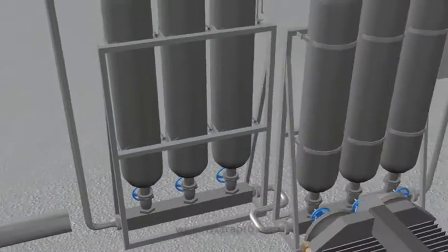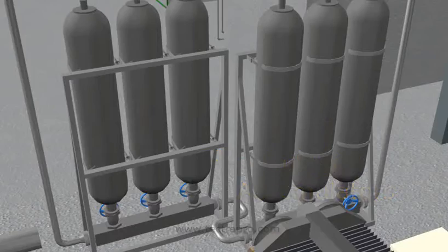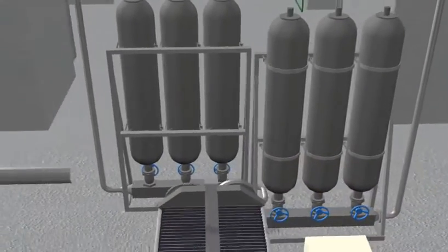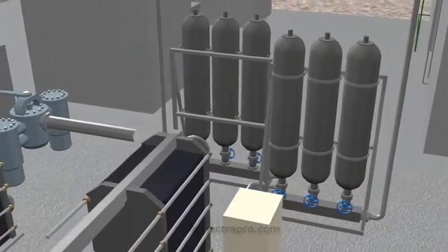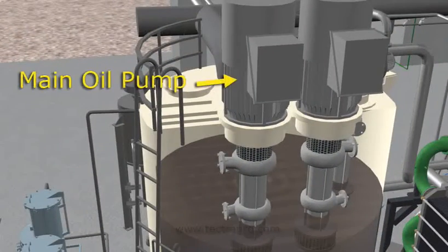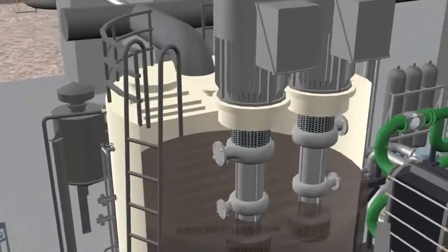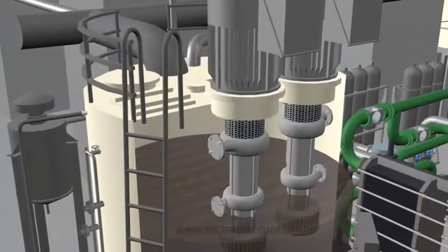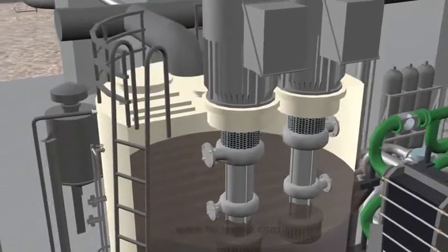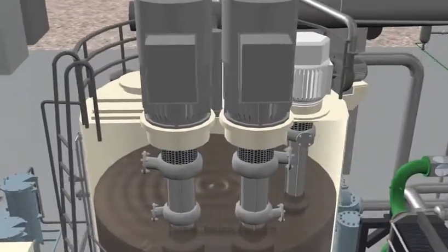There are 6 lube oil accumulators attached to the low-pressure lube oil discharge line. These accumulators help minimize surges in the oil supply to the turbine generator bearings. The AC motor-driven main oil pump is located in the lube oil tank with the motor located on the top of the tank. The main oil pump is the primary supply for low-pressure oil for bearing lubrication and high-pressure oil for the control oil system.